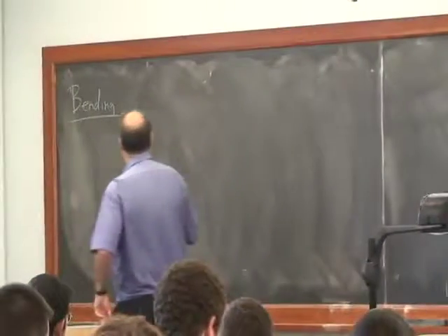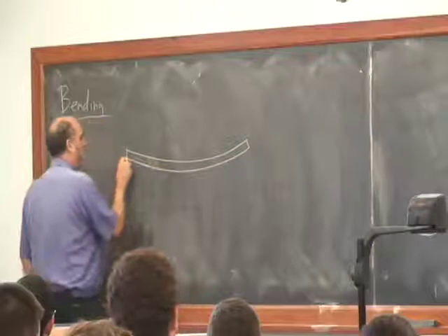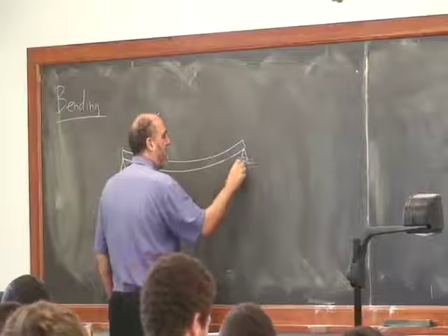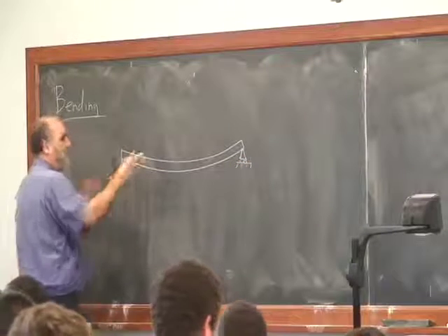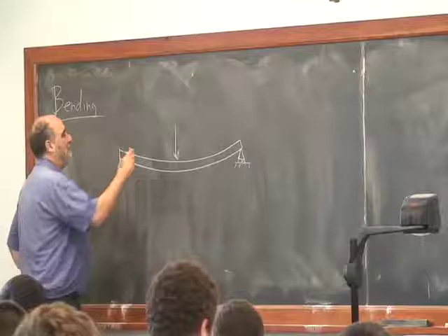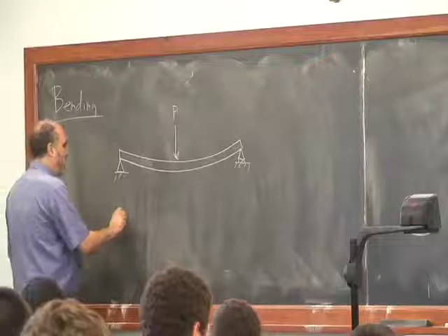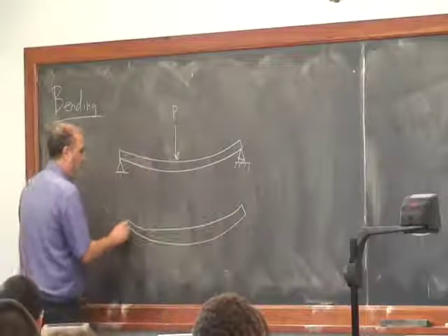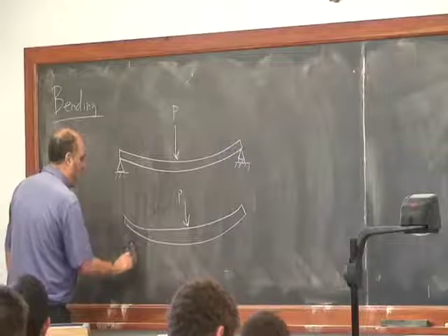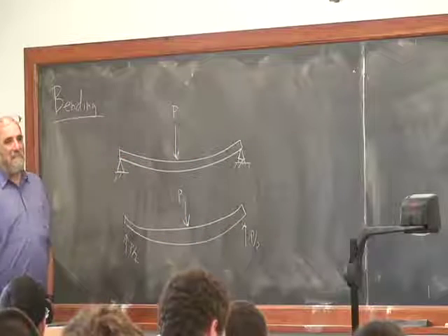Okay, so take this stick here, and what they call this simple bending experiment is you hold it up like this. To make it so-called statically determinate, you imagine there are rollers over here, which means that you don't have to worry about it stretching. And you put some load over here like this, and you see that there's some force on this. Let me call it P, or it could be whatever we want to call it. This thing, if we draw a free body diagram of the whole structure, turns into something like this, with a P here, and a P over 2 here, and a P over 2 here. And we're trying to figure out how much this thing bends.